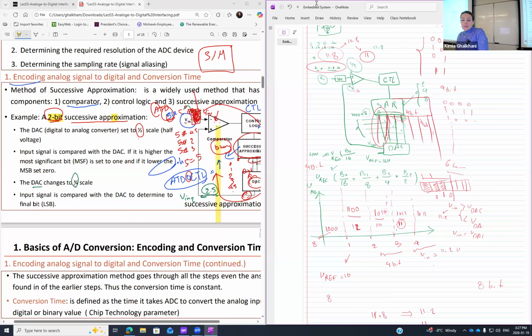And then what is your sampling? This is the sampling. Your plus minus box triangle where you have the 1/2 step. And your comparator: the comparator takes whatever comes from the DAC and compares it with my input to make sure, do I need another step or not? That's what my comparator is doing.